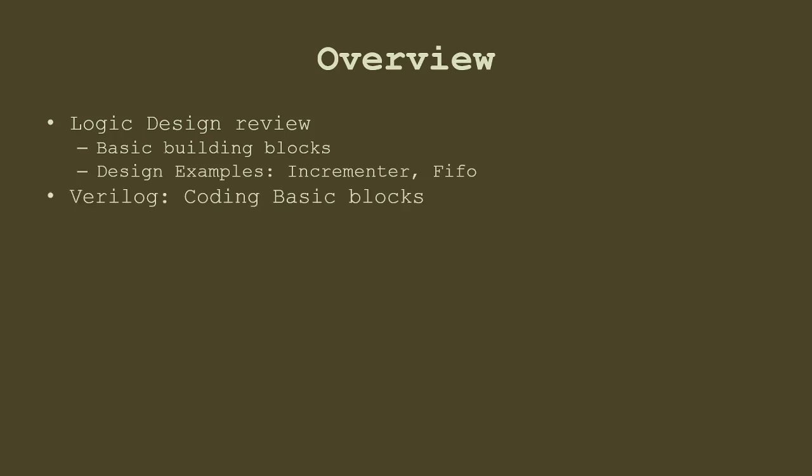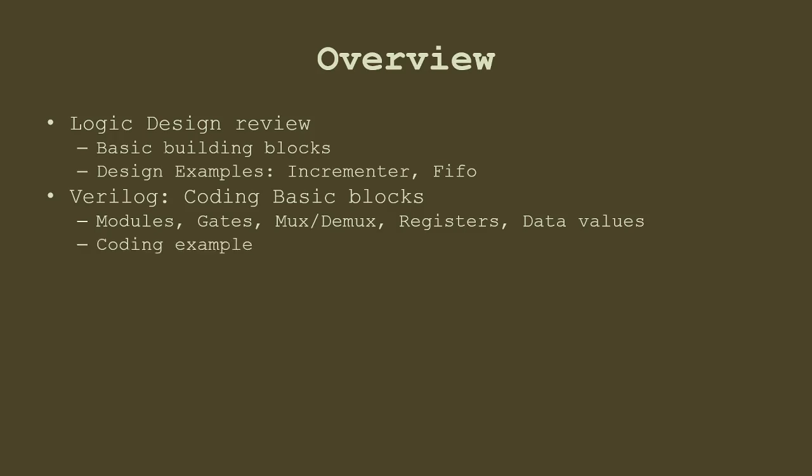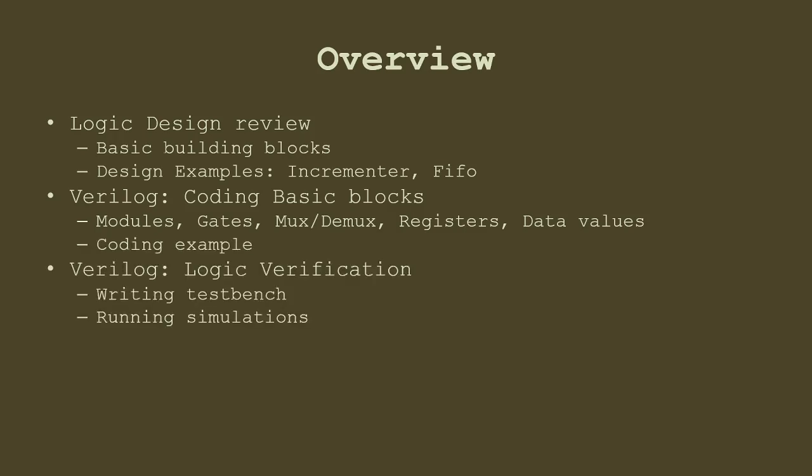In Verilog, we'll cover basic building blocks, modules, gates, mux, demux, registers, and how data values are used, and we'll do a coding example. This will be followed by Verilog for simulation, which is kind of different from Verilog for synthesis. That's the first part.